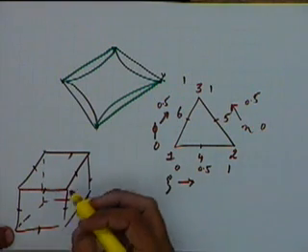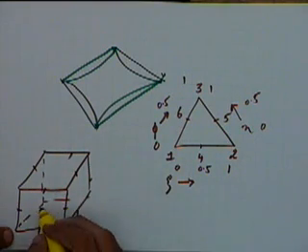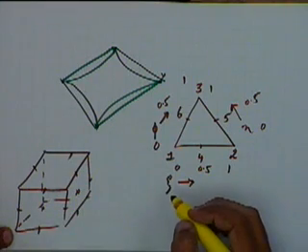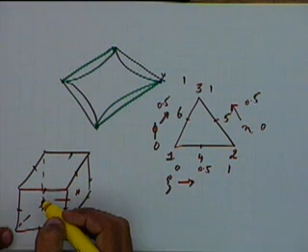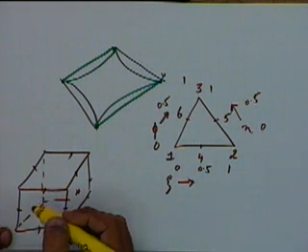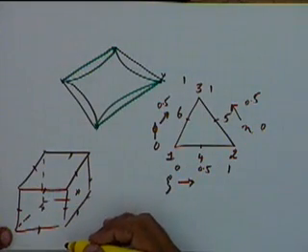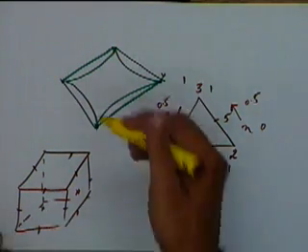You can also have a 27 noded element. At the center of every face you have an extra node: 6 faces plus the center of the cube. You can have a 27 noded cubical element. But then you have to define the 27 shape functions accordingly. The basic process can be the same.